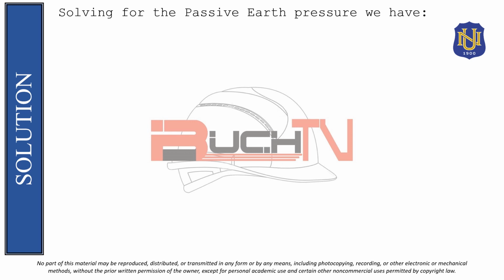After nating makuha yung passive earth coefficient, didiretso tayo sa pagkuha ng passive earth pressure. So, gagamitin ulit natin si gamma H times K sub P. Substituting the values, so we will have 17.5 kilonewton per cubic meter times 6.2 meters times 2.8272. So, itong value na to magka-cancel, magiging meter squared.